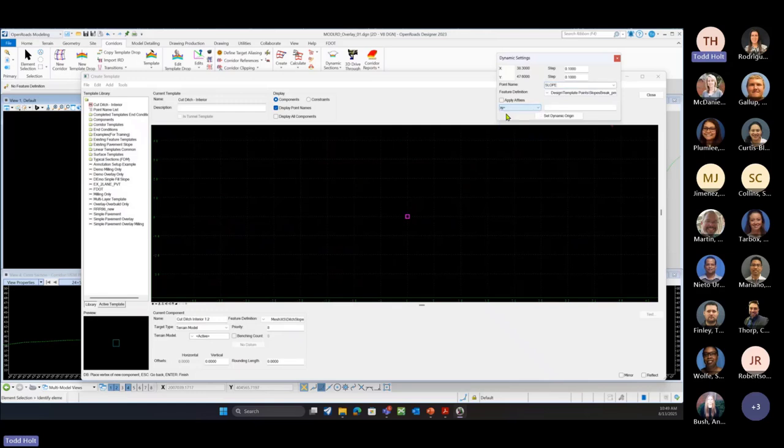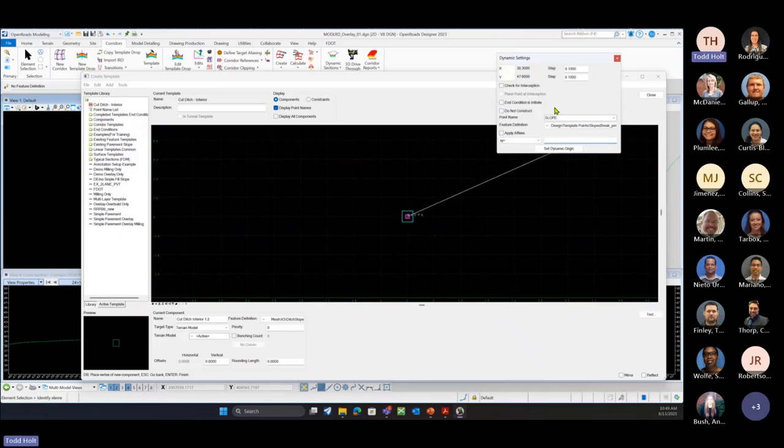Okay, so then we're going to come to our precision inputs. We'll go to X and Y, and we're going to do 0, 0, and then enter. And then in this, we're going to clear everything else out, and it's remembering the settings from the last time. So we want this part to always draw. So we're going to toggle off all of these, or we want this stitch to draw throughout.